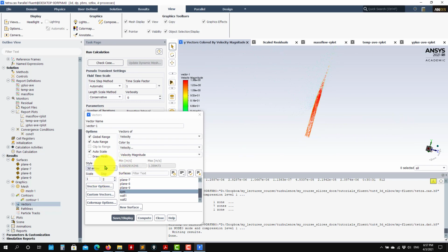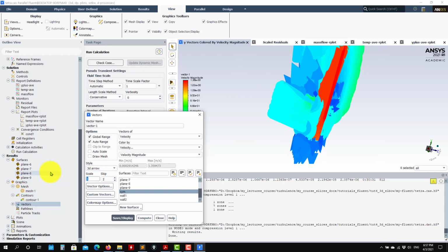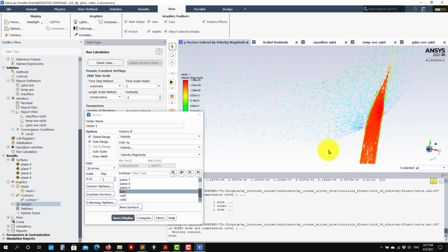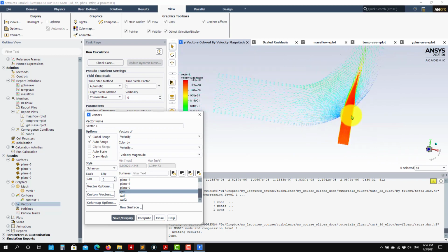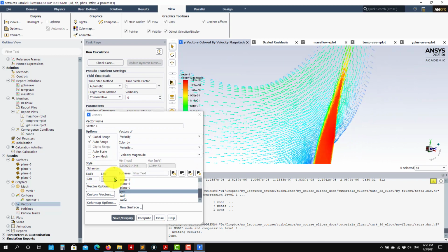Okay. So be careful with that, and let me disable the auto scale, and let me scale by 0.1. So you have all the vectors there. Okay, skipping 2, or if you put everything, see that you have all the vectors. Sometimes you have very large meshes, and this might be a problem. So always be careful when plotting. Increase this one just to avoid crashing your computer.